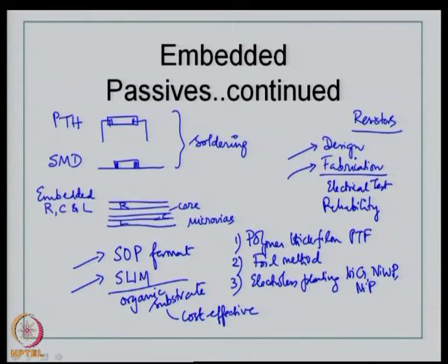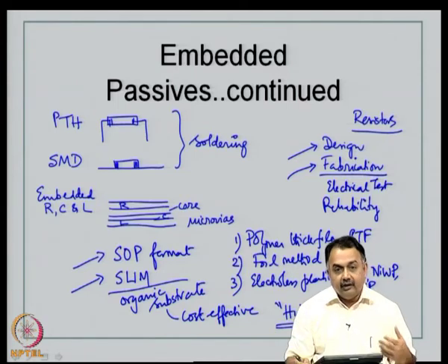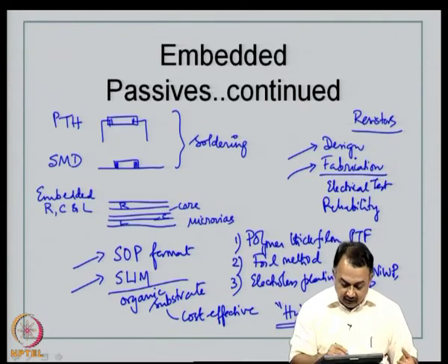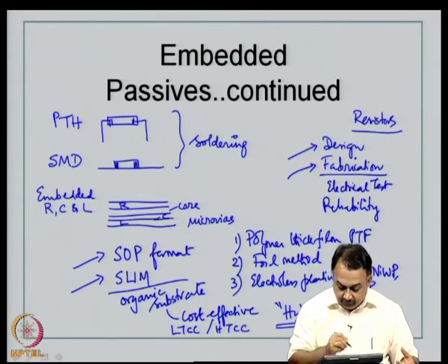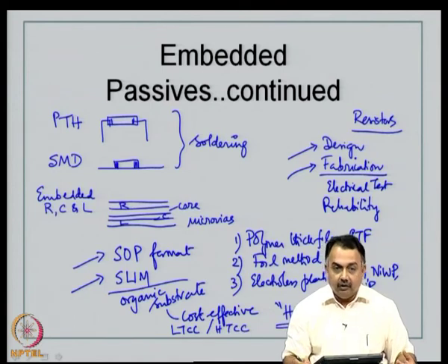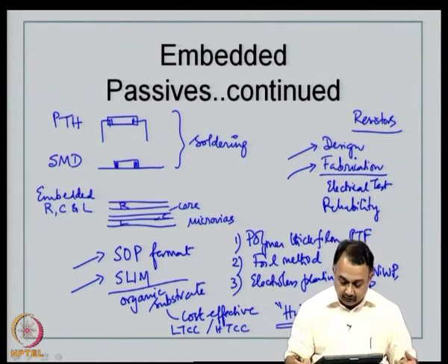Now, if you recall, I also talked about hybrid circuits in the last class, where hybrid technology has been known much earlier, and especially the thick film circuits, screen printing thick films of resistors, copper conductor based capacitors or inductors, and then co-firing them using the LTCC process or HTCC process, and then realizing modules including multi-chip modules.